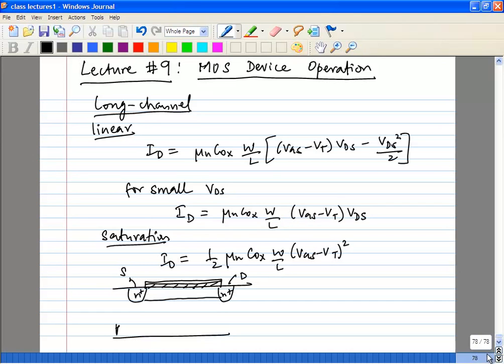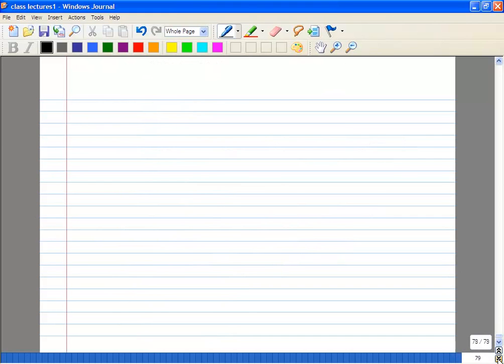With that background, let's start looking at the capacitances of the device. You have probably covered this a little bit in your analog ICs course. At low frequencies, you assume there are no capacitances for the device. You just assume the input is open circuit, you have a transconductance gm, and an output impedance.